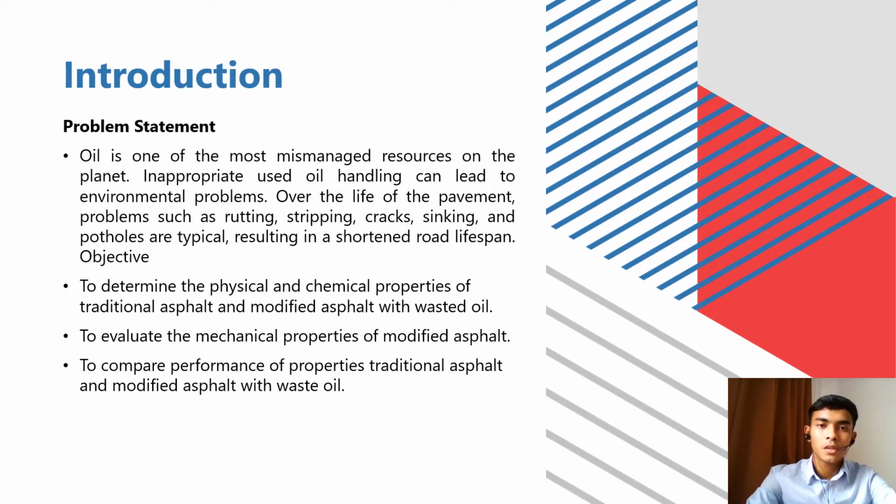I will start with the introduction and the problem statement. Oil is one of the most mismanaged resources on the planet. Inappropriate oil handling can lead to environmental problems. However, waste oil may be recycled in a variety of methods and used in technical applications such as a rejuvenator for asphalt binder. Over the life of the pavement, problems such as rutting, stripping, cracking, sinking and potholes are typical and result in a shortened road lifespan. The addition of a bio-oil to asphalt binder significantly eliminates concerns about non-renewability and binder cost inconsistencies.